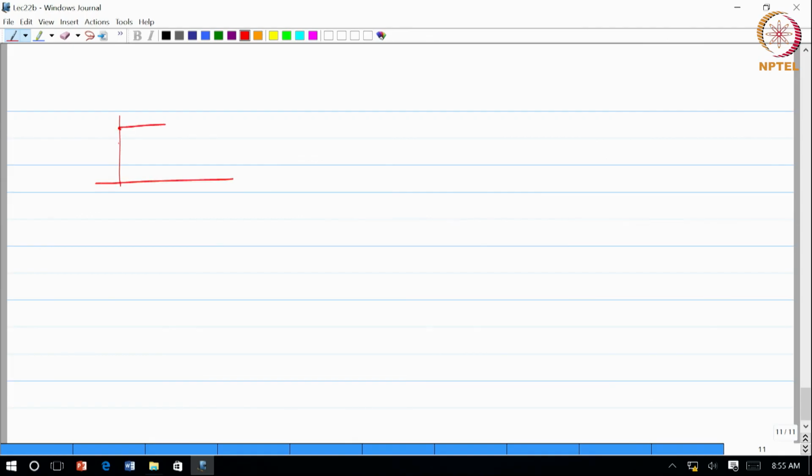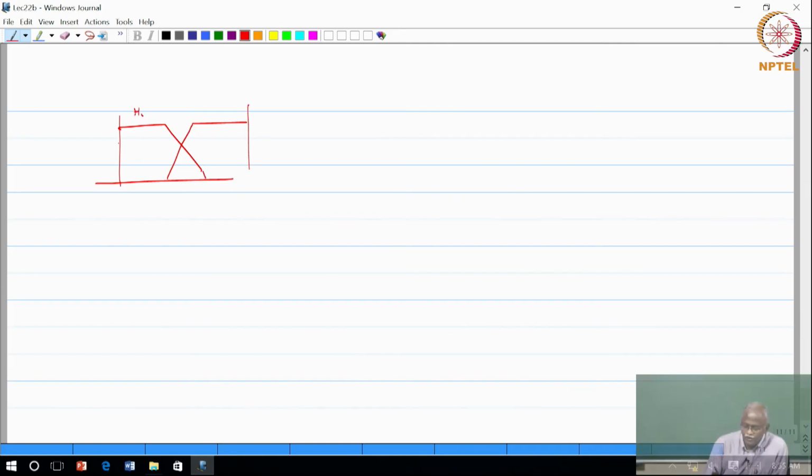And just a last point, what does that actually mean? If I have a quadrature mirror filter, what the condition says is, if this is H0 and this is H1, take the magnitude of H0(e^{jω}) squared. So basically square this, then square the second term, the magnitude of H1(e^{jω}) squared, and add them together.